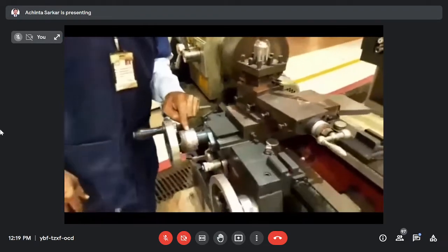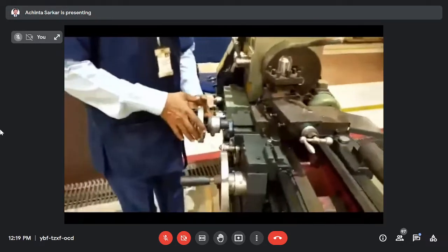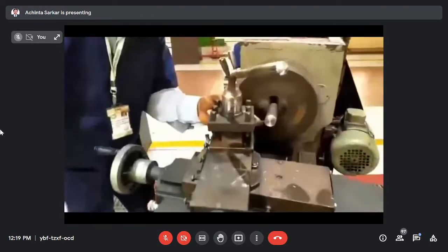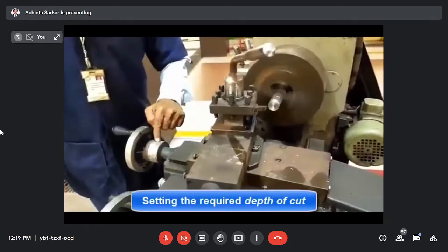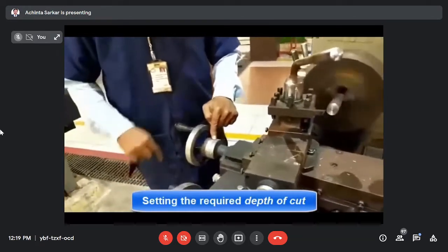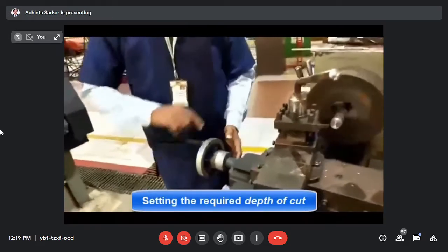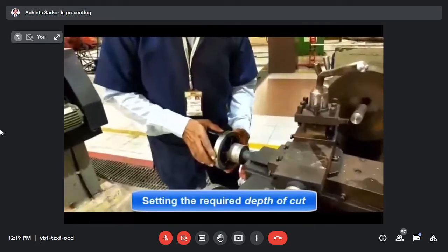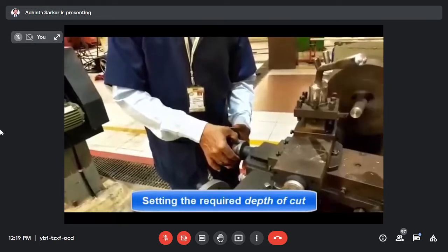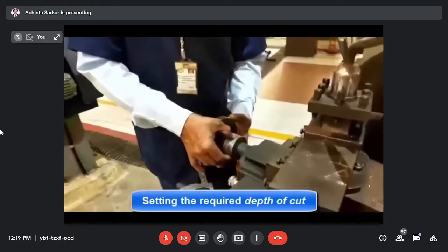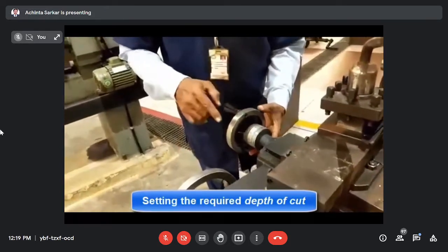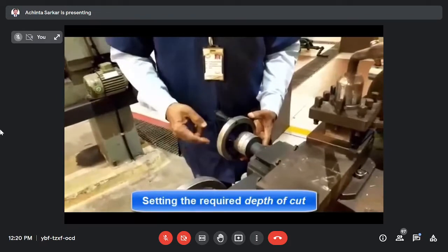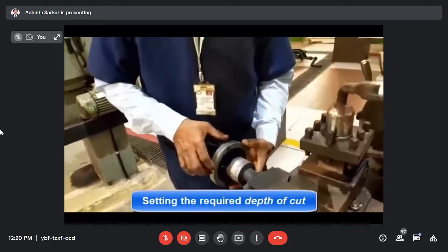Here, 68 will not disturb the cross-slide wheel. The cutting point is moved away from the surface of the workpiece towards the outside, and from this reference position, turn 15 divisions in the clockwise direction. Now, 73 is the reference position, 73 plus 15 divisions is 88.